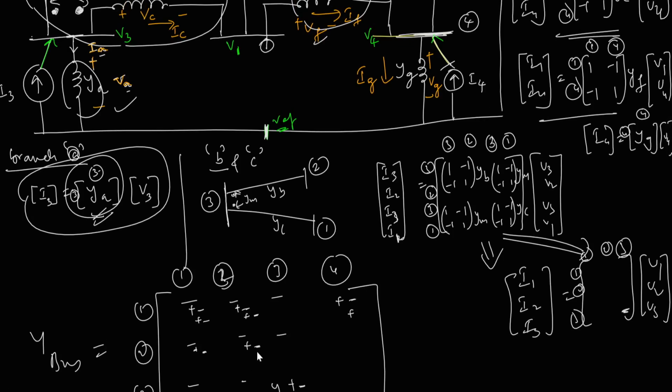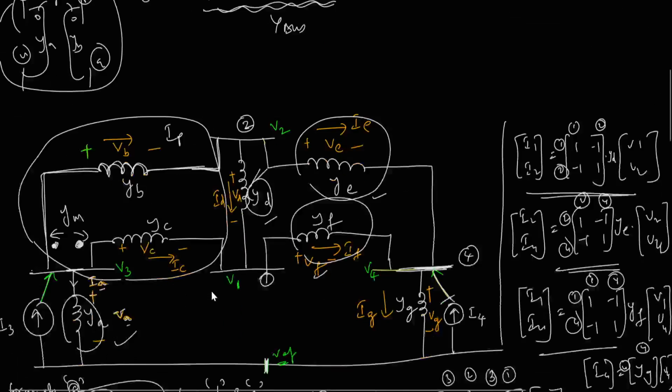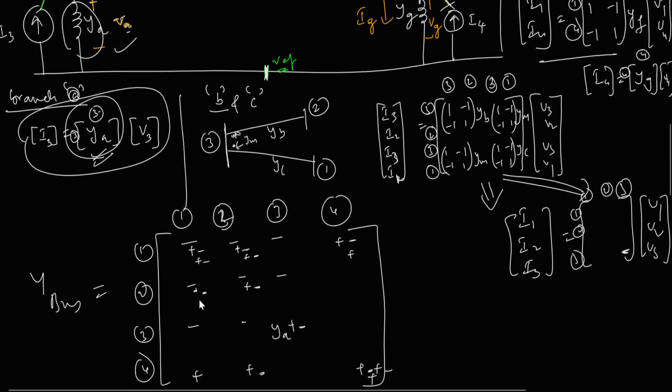Okay, so again take this as a small exercise or assignment too. Take the same line admittances I have given in the previous problem, and try to write down the building blocks like this, and add corresponding to the Y bus elements. If you do and simplify this, you will get a simple 4 by 4 matrix, which should be equal to the previous Y bus you found in the first assignment.